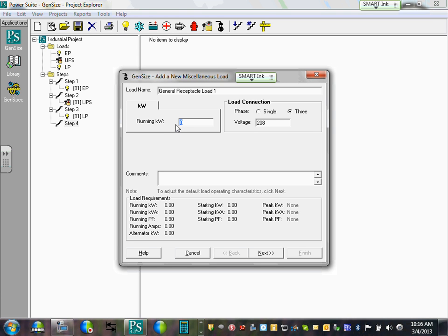And what was the kVA that you calculated for your receptacle from your load calc? 26 kVA, 46 kVA. Now everybody has their own number, and your number will be as accurate as this information will pick. You can rename that, right? It's going to be connected load. RP. I'm going to go on the load calculation. Everybody name the RP receptacle panel.